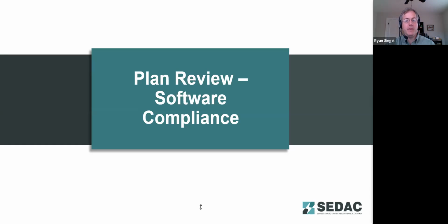And secondly, how can you speed up plan review for envelopes? Include a summary table in plan drawings, include a summary table in the spec drawings or specification documents, reference the spec documents location in the drawings, clearly indicate the air barrier continuity between assemblies, or constantly call your code official for updates.